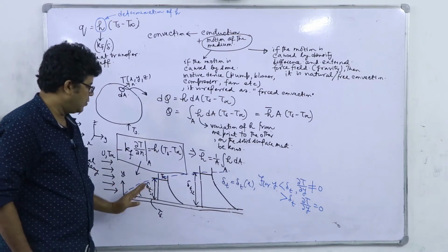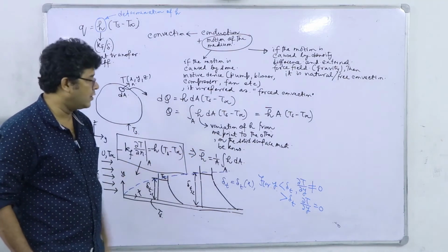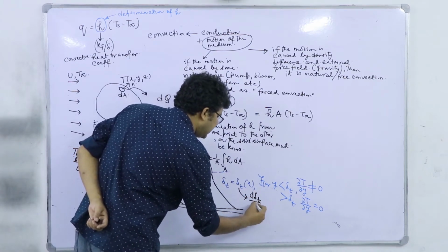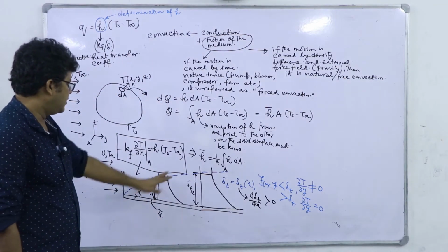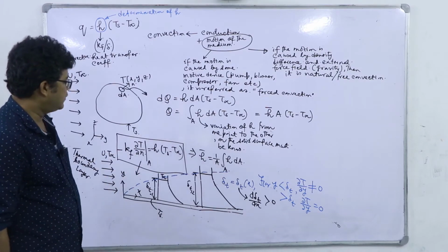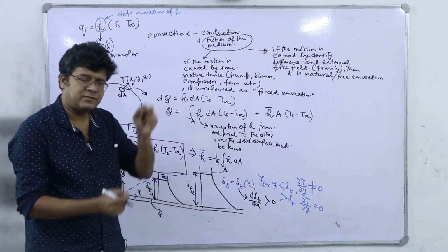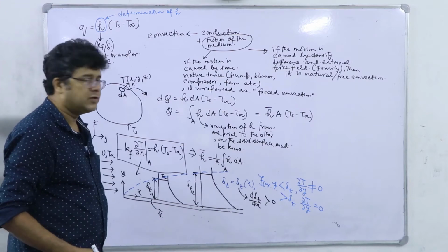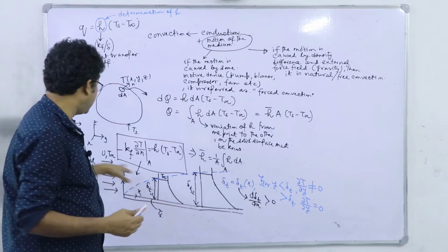And you see what happens: just like the hydrodynamic boundary layer, the thermal boundary layer also grows with x. So basically we can say that d delta T dx is positive. That much we can infer about this thermal boundary layer, its temperature profile, and how it is being defined. Now, this boundary layer thickness represents the penetration of the thermal front, how far this different thermal state is penetrating into the fluid, because the plate has a different thermal state than that of the bulk fluid.